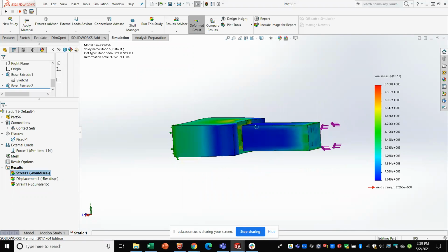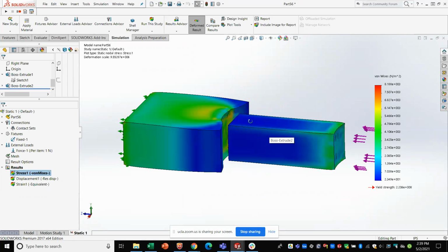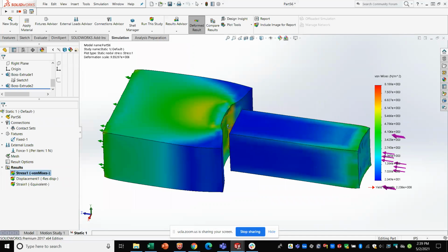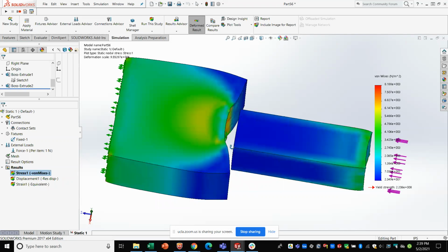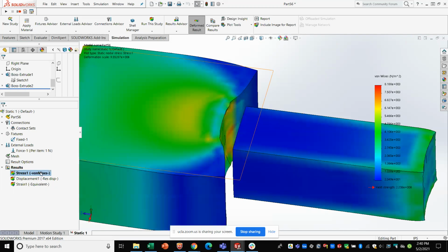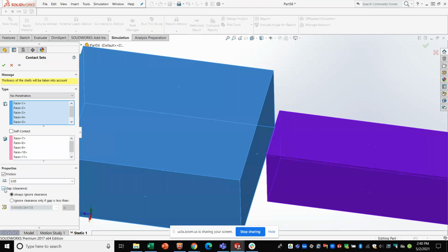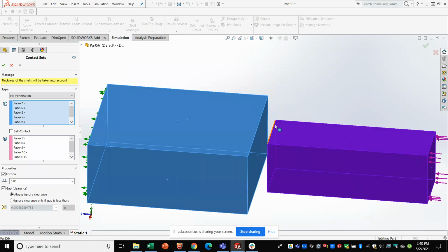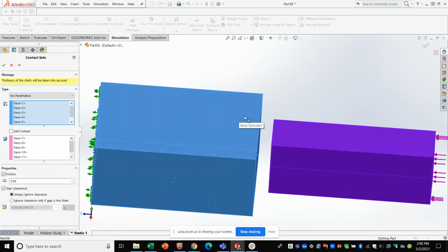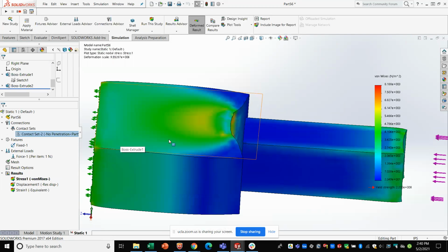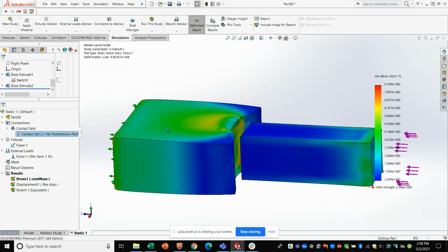No. And now I get really weird results because I declared the gap feature. Because I had this gap checkbox enabled, it's now assuming that an element, say for example here, can touch an element over here. So it gives really weird results.